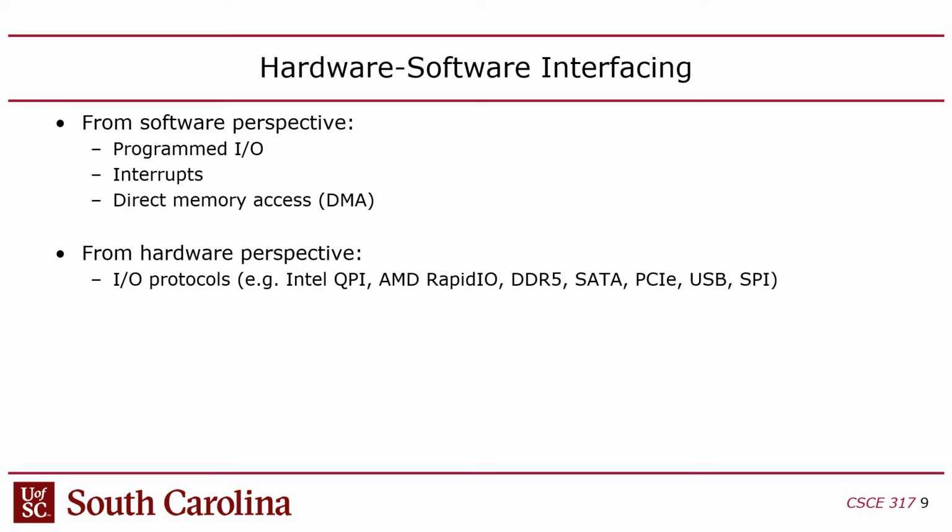And then direct memory access is used for high-speed I/O, which is where you're doing high-speed blocks of data transfer between a peripheral and memory. That's used for hard drives and display adapters. You're not going to find DMA in a lightweight embedded system like an Arduino. They are in Raspberry Pis, but you're not going to find that in an Arduino. It's only for, that's a high performance mechanism, okay? So like I said, these haven't changed in decades. These are the three basic mechanisms that the software uses to talk to hardware, but that's from the software perspective.